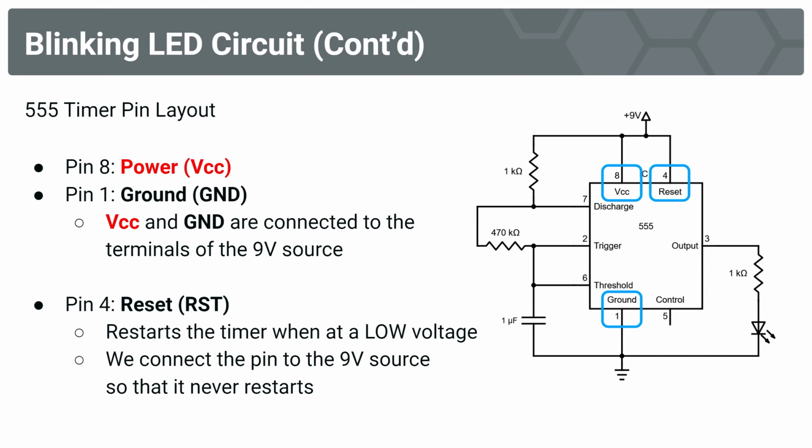and maybe in the context of a specific use case. Because remember, the 555 timer has multiple modes. We're going to explain how it's used in astable mode in a blinking LED circuit. So we're going to go step by step here, starting with our pin 8, VCC. That's our power pin. That's connected to our power source. This is our 9-volt power source. We have pin 1, ground. This is connected to the ground of our circuit.